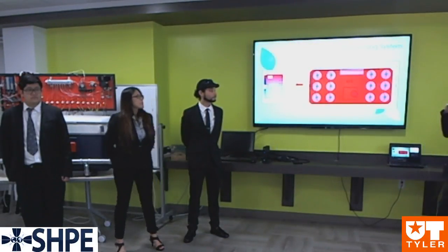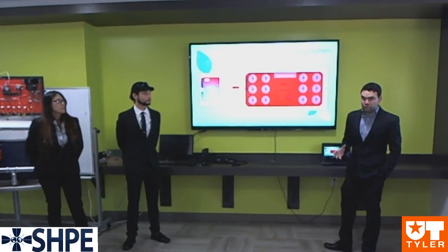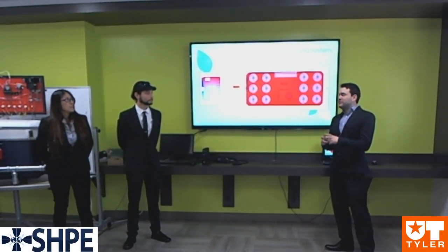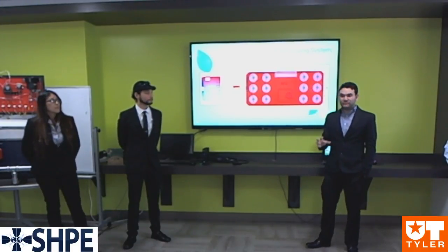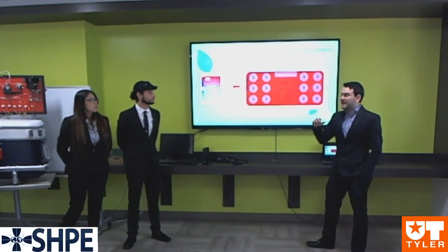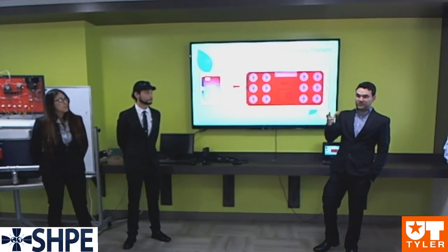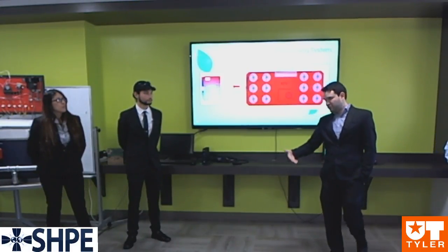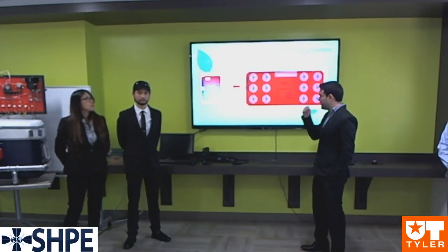Now I'm going to talk a little more about the condensing system. In order to have accurate readings of the CO2, we must have a condenser unit for each one of the vessels. The condenser units will help us maintain the humidity of the vessel at 60% or above. Every time the water vapor tries to escape the vessel, the condenser turns it back into liquid, and the liquid will naturally fall back into the vessel, therefore maintaining that cycle to maintain the ideal humidity that we need.